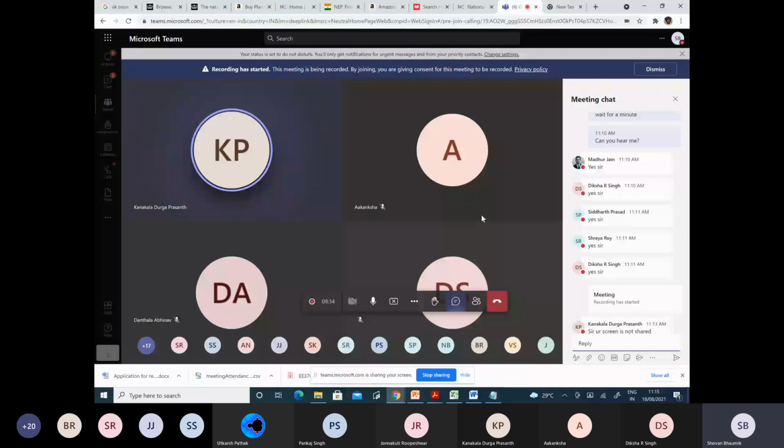So the point I was trying to tell is about the zero order instrument, and for the first order instrument I said that the example is the thermometer. And I gave the reason that if you put the thermometer in contact with the temperature, the thermometer mercury will rise gradually, slowly, and then it will stabilize at some point and reach the steady state. It will no longer rise, and that is the temperature we measure.